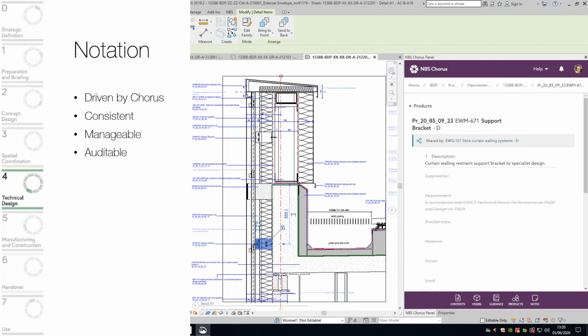So when we've done our 3D model and we've got the geometry correct and we've augmented it with 2D objects, etc. as well, each one of those objects, systems, families is all linked through to specifications. So it pulls from the specification the Uniclass code, the T-sheet tag, the description, and the designer's responsibility. And then we can put it on the drawings. And this gives us a bit of reassurance that fundamentally every drawing is consistent. And as long as we've spent time thinking about how the data is structured, then we can be pretty confident of the end result, and it helps reduce those little errors.